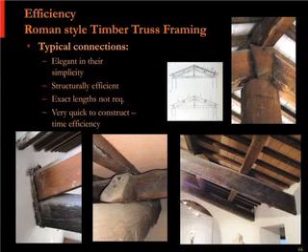So they're often revered, but they do have some drawbacks as well. I mean, the deep cuts do weaken the wood member that you cut into. A lot of the structural failures we looked at in buildings like this tend to occur at the connections and at the cuts. Very time-consuming to build and inefficient time-wise, and I would say structurally, because of the very deep cuts in the main members.